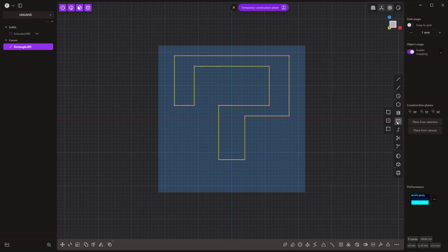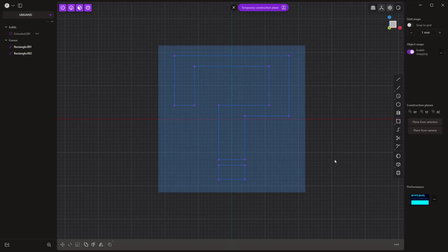Then in our corner rectangle, hold down the left mouse button and tap shift, come over here, tap shift again, right click, and now basically we have everything. I'm going to move over to my vertex selection, which is 1 on our numbers. I'm going to box select everything, and then I need to remove a couple. So with these question mark blocks, the outside corners here are going to be a larger chamfer. So I'm going to hold down Control, deselect those, and deselect this one as well.